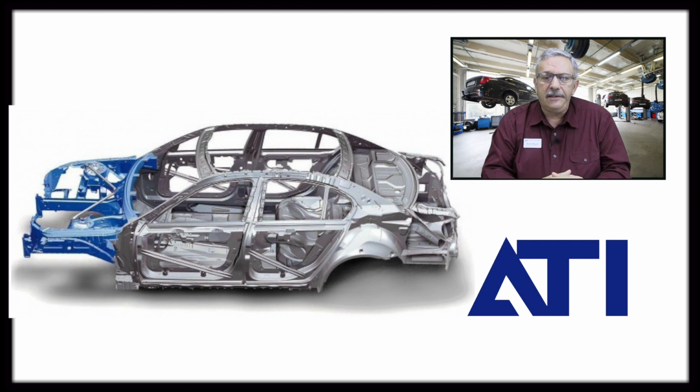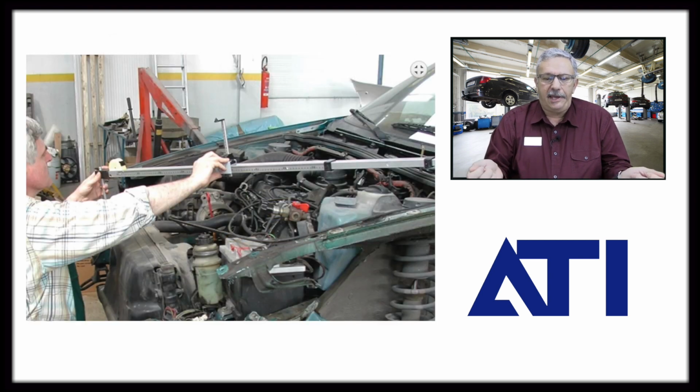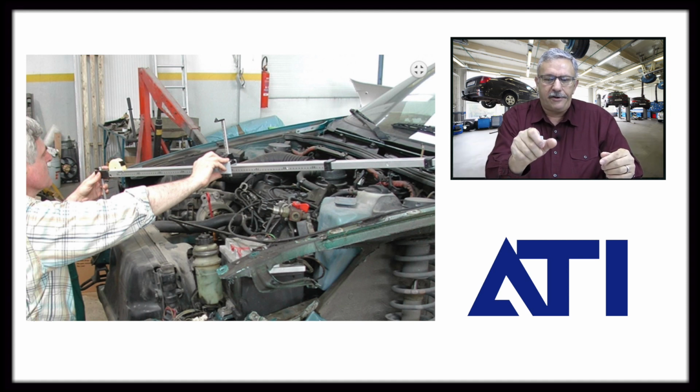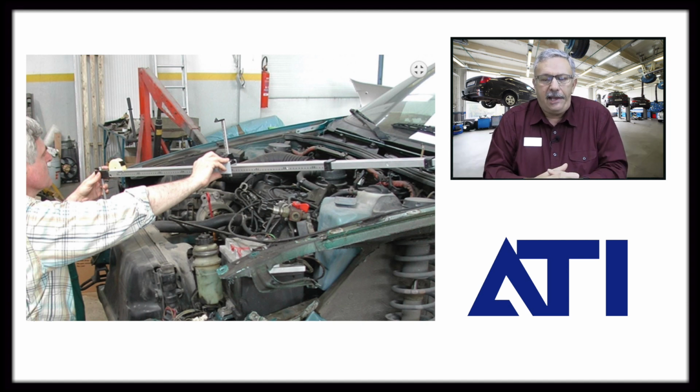But the next thing that's important to us, and is critical in reconstructing the vehicle, is structural measuring. There are all different kinds of equipment and measuring devices that can be used, anything from a basic tram gauge, which is a mechanical system, depending on how much money you want to spend. The tube, as you pull it apart, will give you in metrics what the measurements are in the center, or some you just take a measuring tape and measure end to end, and that gives you your measurement. But that would be your most basic system.